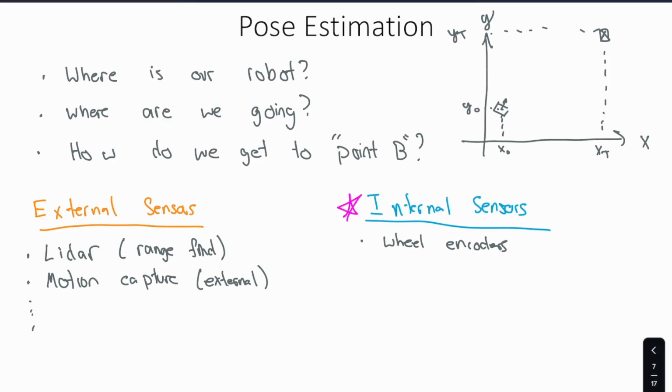And it's not doing something like checking to see if we're actually making progress. The wheel could be not touching the ground. Maybe we got high-centered, the robot got high-centered. Or maybe it's slipping and a full rotation of the wheel, which is measured by the encoder, doesn't actually end up moving the robot that same distance.